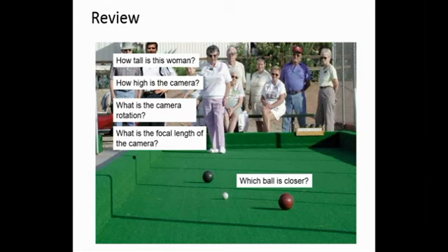First, the first thing we'd want to do is construct vanishing points. So we can measure the 3 vanishing points based on the orientation of this pitch. We've got a couple of walls there that we can use, and the tops of the walls, to find a vanishing line in the longitudinal direction. We can use the lines on the fence here on the right side to find the vertical vanishing point. And then we can use these parallel lines on the back of this pitch to find the horizontal vanishing point, for example. And there's also some fences that we could assume are horizontal.